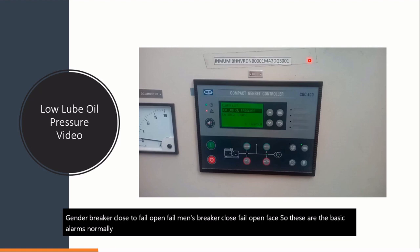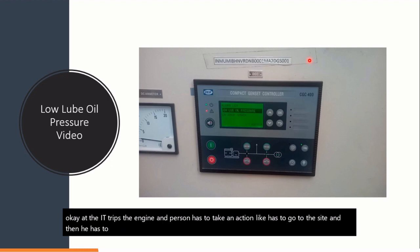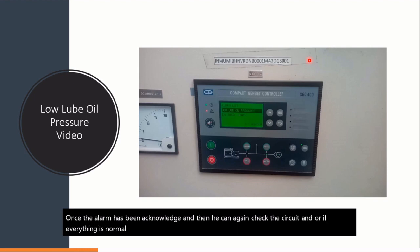And what is the role of the operator? As soon as this alarm comes, it trips the engine and a person has to take action. He has to go to the site and then go to the equipment, and he has to acknowledge the alarm. Once the alarm has been acknowledged, he can again check the circuit, and if everything is normal, then he can restart the DG by putting it in manual mode.